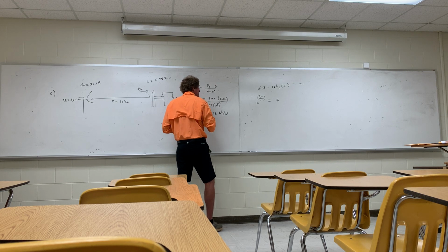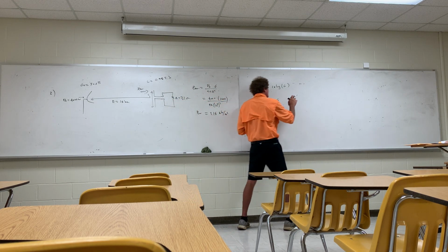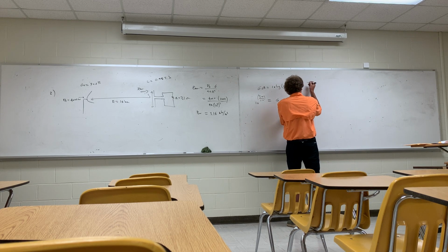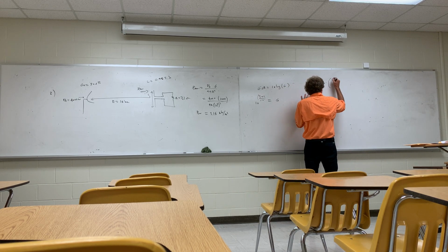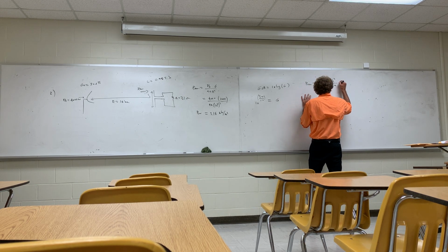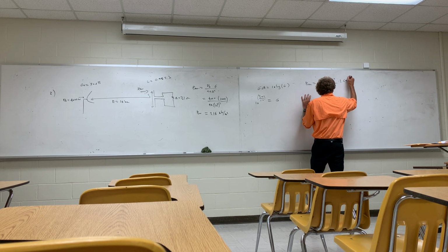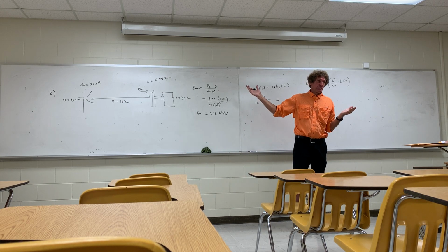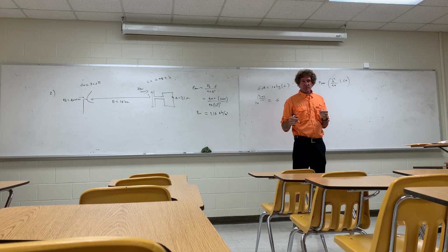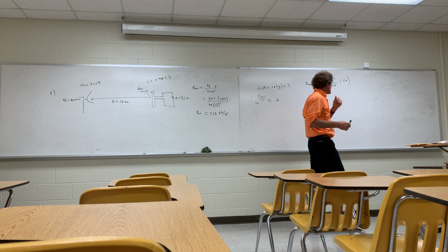After that, you need the actual power received. This is the power received that's not at the load, but by the antenna itself. So P received is really going to be the power density we just calculated times the aperture of that antenna, which is lambda squared over 4 pi, times the maximum gain, which would be 1.64. I gave you the gain equation, but because the angle is 90 degrees, it's the max gain, it's just going to be 1.64. You didn't have to do any angular calculations.